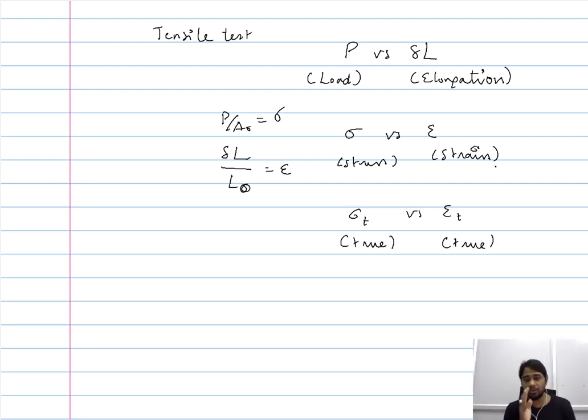However, now it is important for us to realize in the context of practical tensile testing that even though the most accurate way of representing the tensile test is by means of using true stress and true strain, it is quite difficult for a few reasons. One of the reasons is the definition of the true stress. It demands the calculation of the instantaneous area.